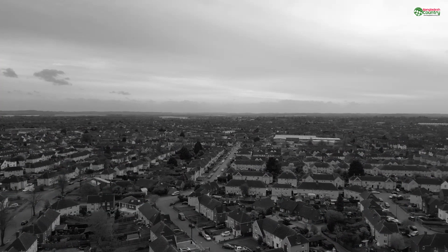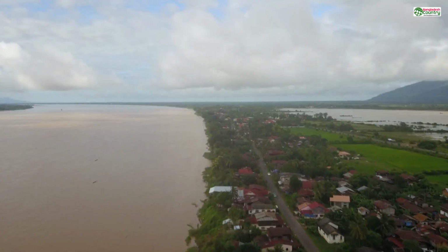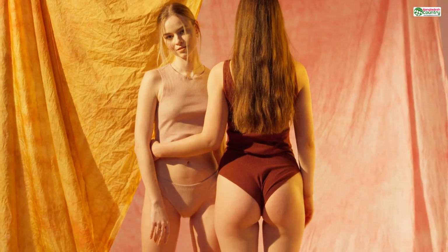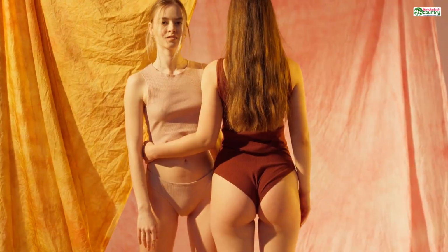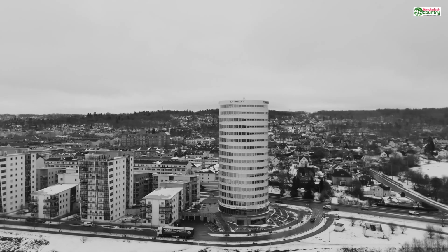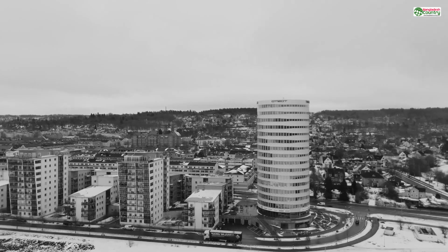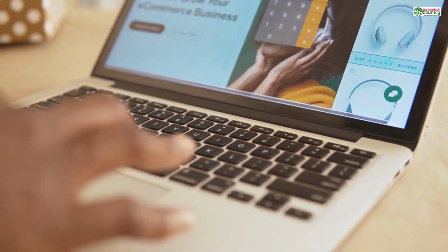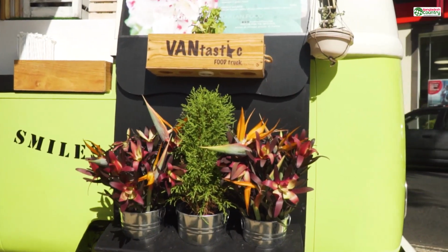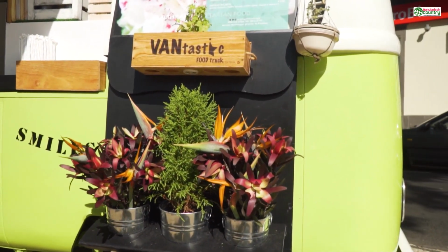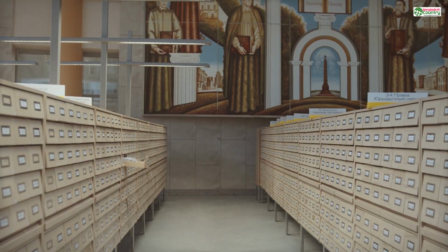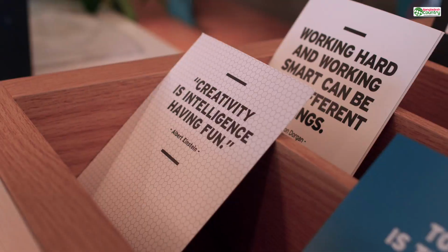However, many online printing services know this is a common problem, so they've built in a life raft. When you upload your model, you'll often see input boxes showing the model's dimensions. If your model uploads and says it's 4 millimeters wide, but you know it should be 4 inches, you can often just type 4 in the box and change the unit drop-down next to it from mm to in. The website will do the conversion for you and automatically scale your model to the correct size. This is a fantastic quick fix. But be warned, it only fixes the model for that specific order. The original file on your computer is still the wrong size. Best practice is always to fix the source file.